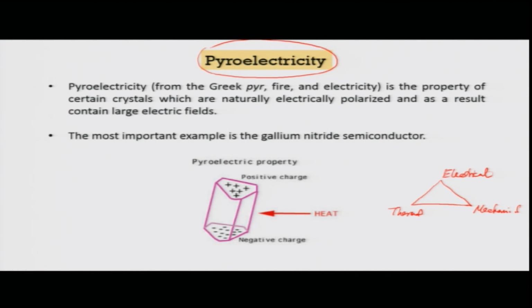But in this case, if you consider that these three fields will constantly interact in a piezoelectric material, that means electricity can produce thermal effect and mechanical effect, we know. Thermal field can produce mechanical effect, we know. Mechanical effect will produce electricity in piezoelectric material. Mechanical effect can also generate heat and thermal effect in the system. And the most interesting thing is that the thermal effect can not only generate a mechanical field, but also an electrical field. This last arrow is actually our pyroelectricity.